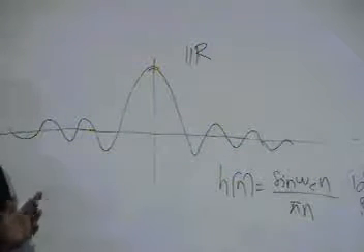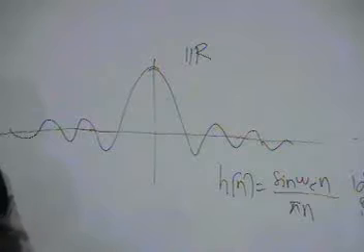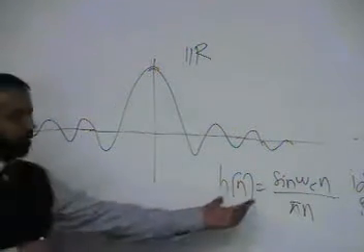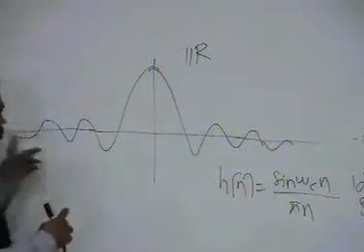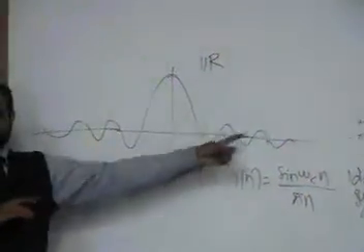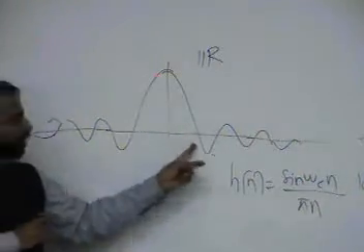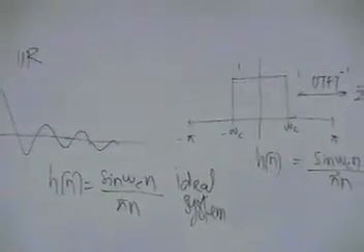So you use convolution summation. Anything which you cannot describe using the difference equation, you implement as a convolution summation. If you apply it as a convolution summation, it's the same problem. It is non-causal and requires all the future samples and all the past samples to compute one output sample.